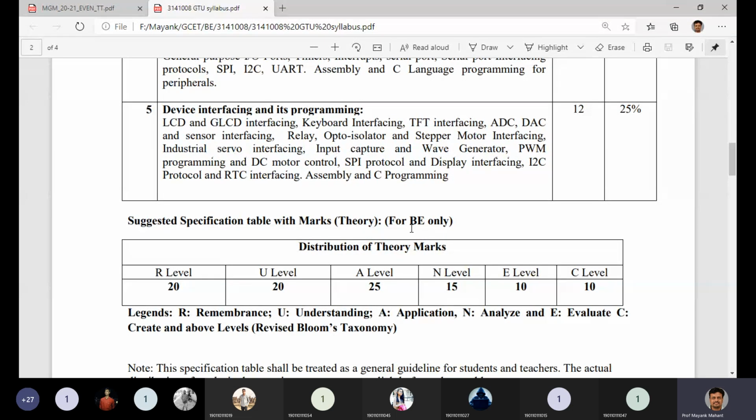All sensors generally give data as an analog signal, and to process this information I need to convert it into digital form. So how can you interface ADCs and DACs with your microcontroller? An 8-channel ADC is already available in your AVR microcontroller, so you can use it to connect sensors.